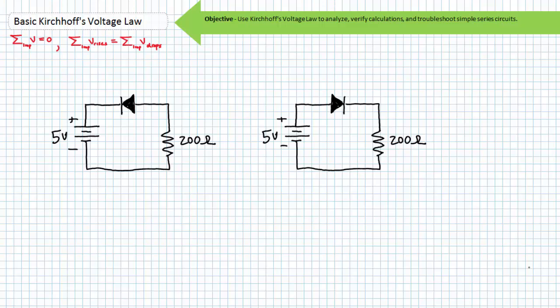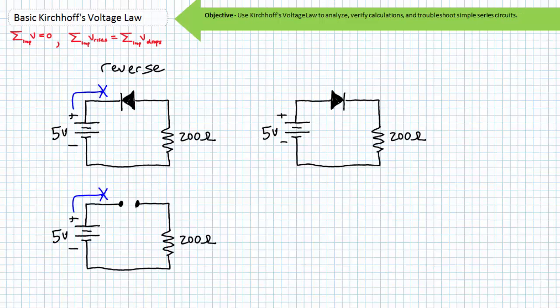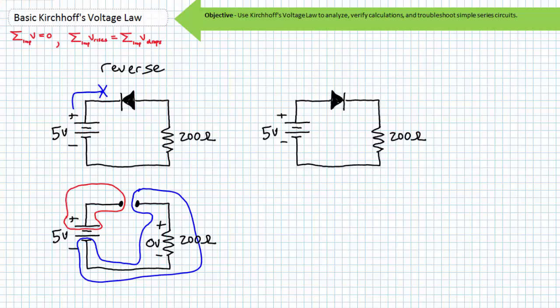They are electrical check valves, in that they do not allow current flow in one direction and do allow it in the other. When reverse biased, i.e., when conventional current is trying to flow counter to the arrow indicated on the schematic, they are an open circuit and no current can flow through the diode. If there is no current flow through the diode, there is no voltage drop across the resistor. Where does the voltage drop occur? Obviously, the 5-volt voltage drop will occur across the open, in this case, the reverse biased diode.